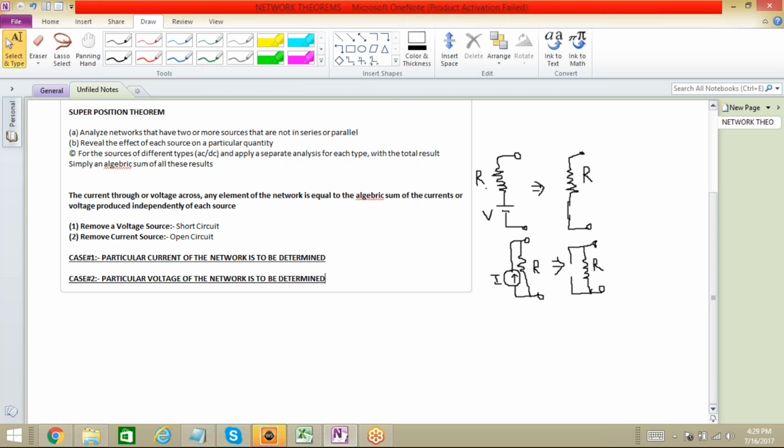When the effect of each source has been determined, those voltages with the same polarity are added and those with the opposite polarity are subtracted. The algebraic sum is determined, and the total result has the polarity of the larger sum and the magnitude of the difference.